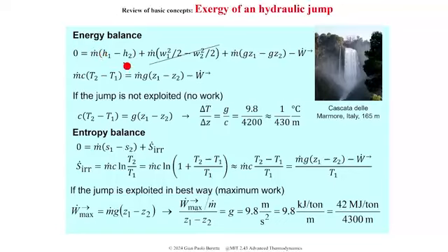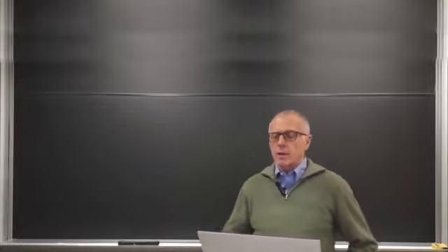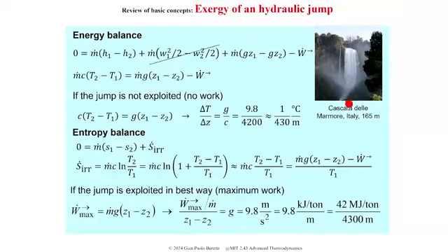Also, if you recall our formulas for the ideal incompressible fluid, the change in the enthalpy is equal to the specific heat times the change in temperature. There would also be an additional term, the specific volume times the change in pressure. But here, the water up and down is at the same atmospheric pressure, so that doesn't contribute. So this is what we are left with.